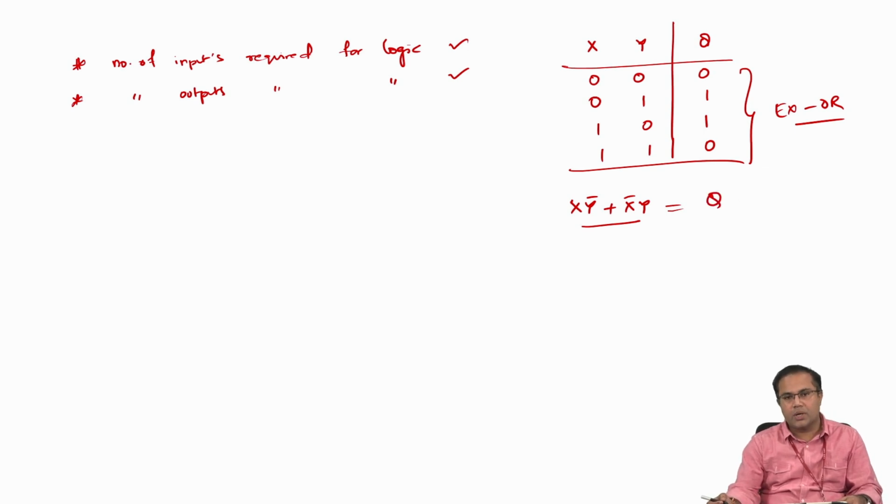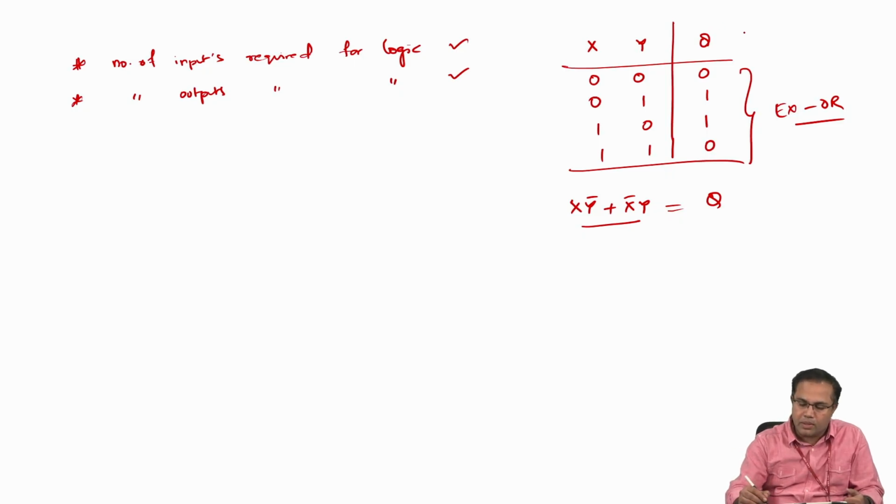Now suppose you have a different application like three inputs and one output, then just list out all your combinations and list out your requirement. What is the output you wanted, and from this output how to get the Boolean expression. In digital logic there is a standard method called the Karnaugh map.